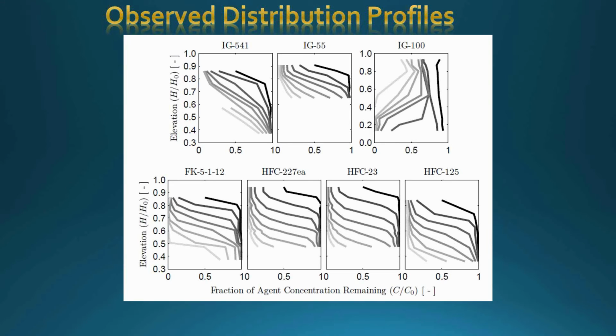No discernible interface could be found using 3 discharges. So we have been always recommending for the last 10 years that nitrogen, or IG100, only be used in the continuum mixing mode, and that the density difference of the agent is used as the driving force, which we still maintain, and our software still runs that way, and it still works fine and gives you good results.